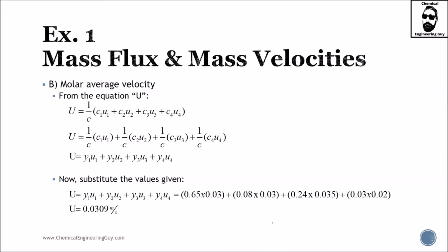We need to calculate the molar value, and this is more interesting because we don't need to get messy with molecular weights. We are given directly the molar compositions and so on. Now, instead of densities, we're going to be using concentration, and you know that the concentration can be calculated as the pressure divided by RT.